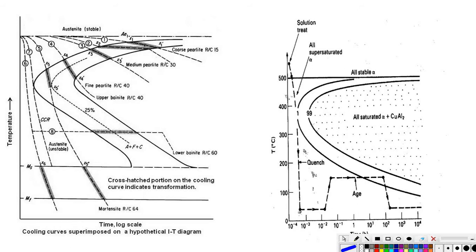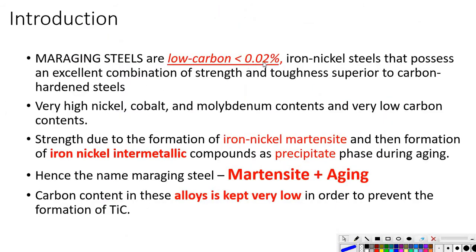Okay, so we got martensite, and in an ordinary case the martensite formed is very hard and brittle, so we cannot use this martensite for applications where toughness is involved. Because of the brittle nature, there is a chance of the martensite breaking. So we cannot use martensite for different applications in modern engineering conditions.